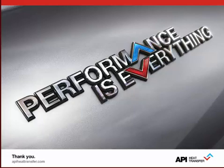30-degree pitch is a very common one, but we could call it the standard. And then you vary from there based on things like pressure loss through the exchanger. While you can vary baffle spacing and cut to help with pressure loss, the tube pitch can also be used for that, as well as bundle entrance velocities. So based on how the tubes are oriented, the fluid dynamics will impinge on the tubes with a higher velocity with certain pitches as opposed to others. So you can adjust that to eliminate that problem.